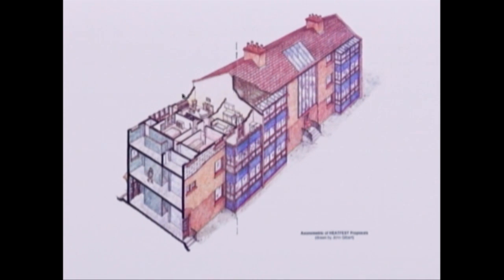The other weak link in the scheme of things was the way people, having got a relatively inefficient heating system by today's standards, set their thermostats. Now that would still be an issue today, regardless of how efficient the boiler was. What we found at East Hall was that people who set the thermostat to a comfort level in the living room and didn't really make much use of radiators in the other spaces were by far and away more efficient than the people who set their thermostat high on every radiator in the house.